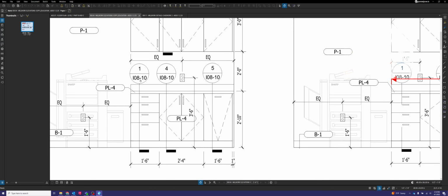Yep, really that's pretty basic stuff right there. Looks like they're using this as a generic section because they have a stone top on here. As we looked at our drawing in elevation view, they have it clearly called out that it'll be PL4 for the countertop, so it'll be laminate, meaning that this hatching is going to change to be our standard MDF hatch instead of our stone or solid surface hatch. Same for the backsplash shoe, that'll also be PL4, so that hatching will change on our drawing here, but otherwise really not much to look at there.